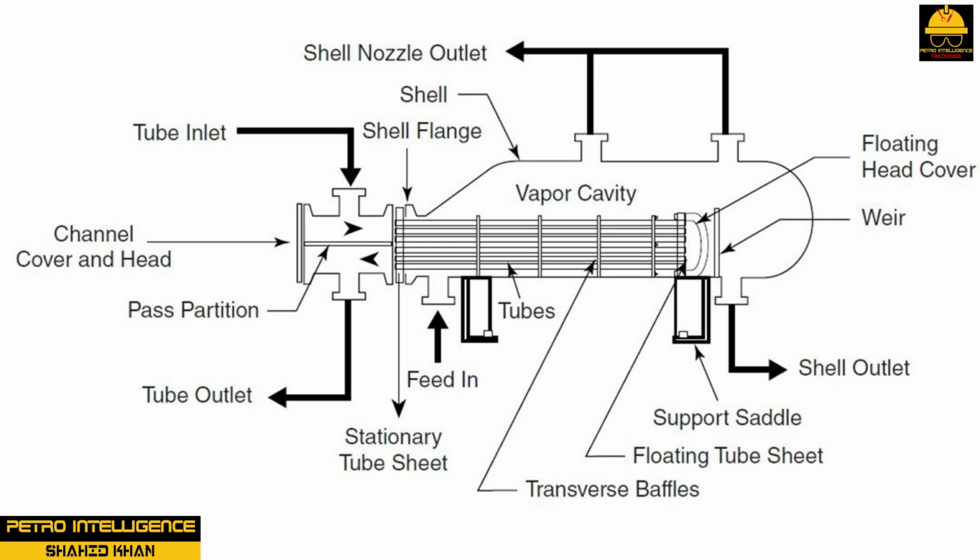A weir contains the unflashed portion of the liquid in a reboiler. Excess flow goes over the weir and is recirculated through the system. Kettle reboilers are easy to control because circulation and two-phase flow rates are not considerations.